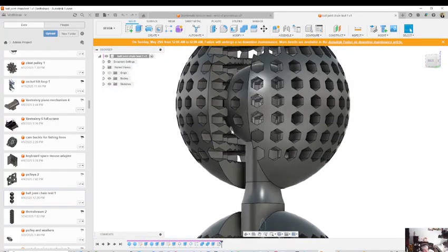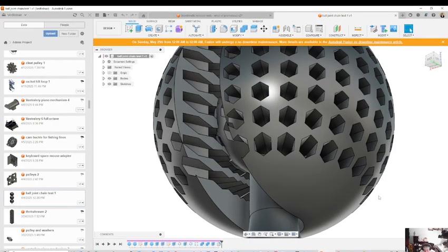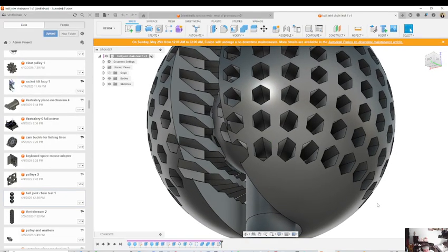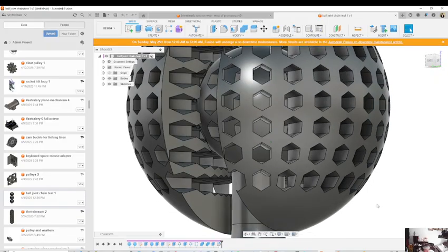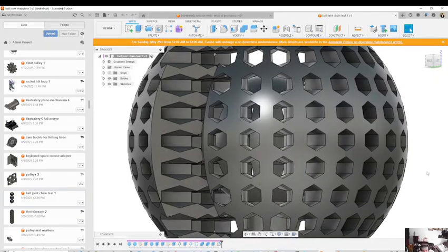But anyways, I tried to go with the tightest tolerances I could. I ended up figuring out that the tightest tolerances that I can print while still maintaining mechanical functions is about 0.2 millimeters. But that is also very at risk of having printing failure issues.